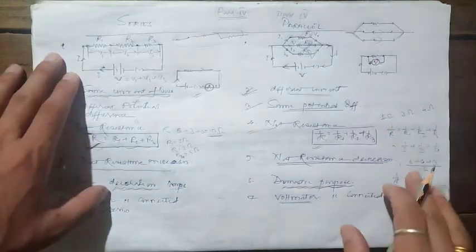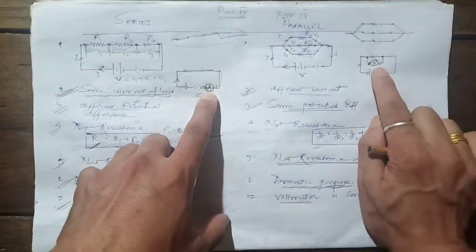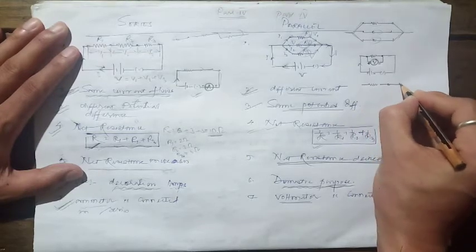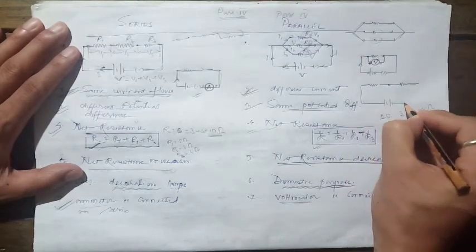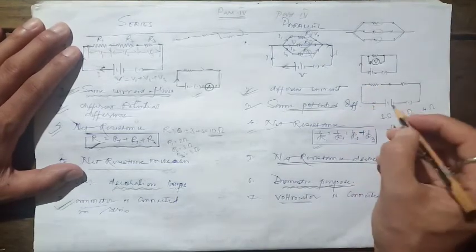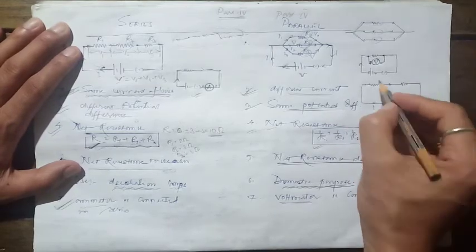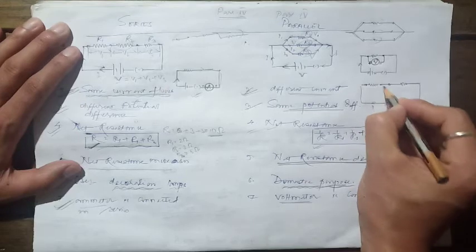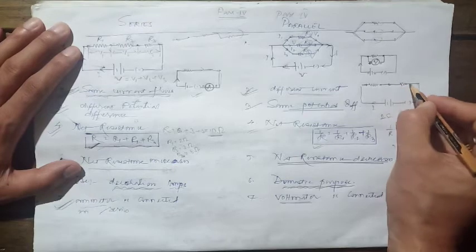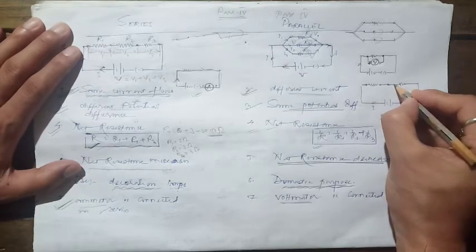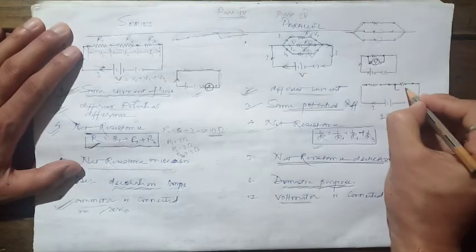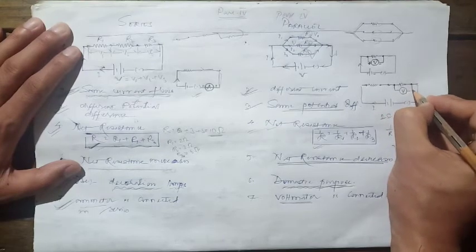So now students, we know the ammeter should be connected in series and the voltmeter should be connected in parallel. Now students, let's take one more circuit to understand the proper connection of this voltmeter. Suppose I have two resistors in this circuit. A certain amount of current is flowing through this circuit. I want to know how much potential difference is consumed by this resistor, or the potential difference that develops across this resistor. To know that, I'll be connecting the voltmeter across the terminals. Suppose this is the voltmeter.